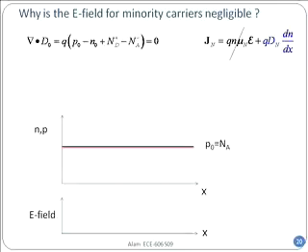Now, in equilibrium, I can also say that the minority carriers, which is the number of electrons, is equal to Ni squared divided by Na in the extrinsic region, right? I'm assuming full ionization, not in the freeze out or intrinsic region. Okay. N0 is a very small number, right? For example, if P0 is 10 to the power 18, and if it is in silicon, what is N0? 100, because Ni squared is 10 to the power 20. And so, N0 is actually a tiny, tiny number. Fine, but it is flat, uniformly doped, and together they make the electric field zero.